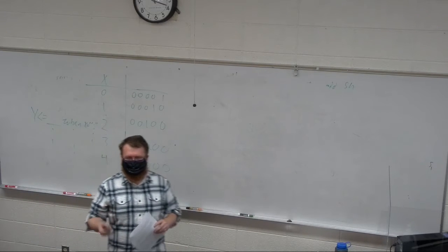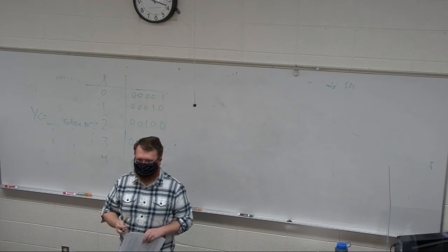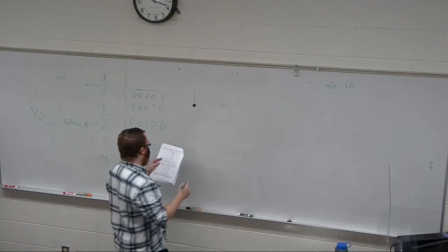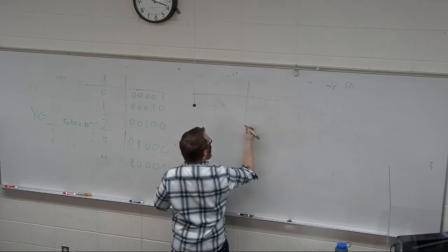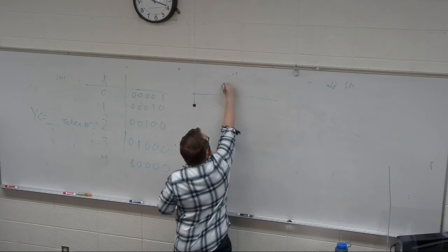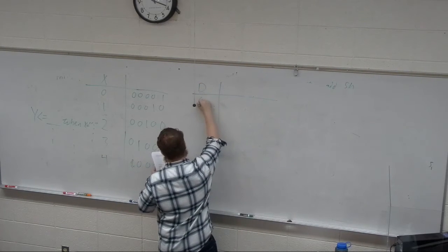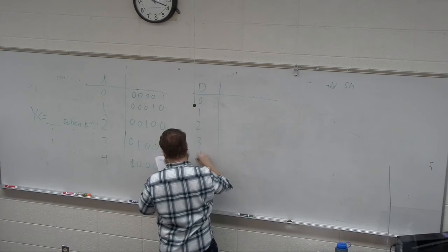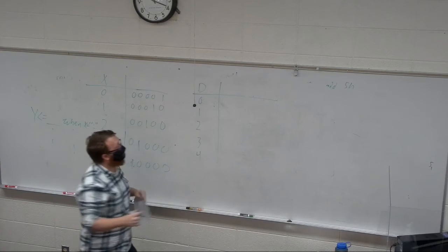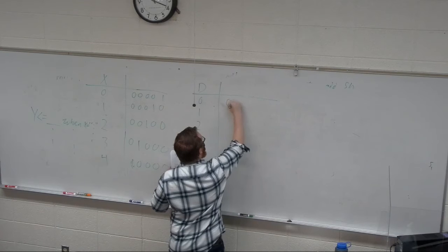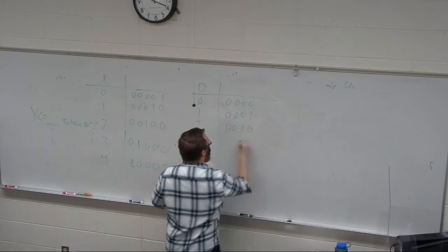You're going to encounter this a lot. Now, BCD is quite useful, but it is a little bit wasteful. So what BCD does is it says that, sorry, my brain is not top notch today. Okay, here we go. If this is my decimal, I'm going to encode each of these in 4 bits, such that 0 is just 0, 0, 0, 0, 1 is 0, 0, 0, 1, and so on and so forth, right?